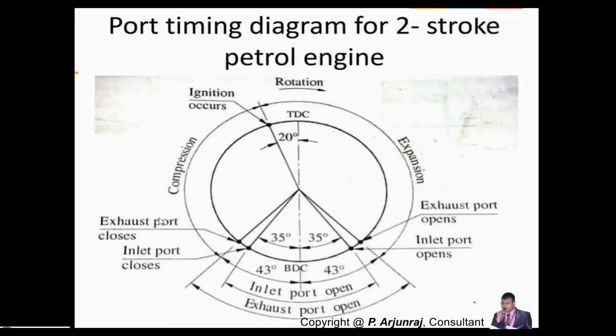The transfer port is the one which will transfer the air and fuel mixture to the combustion chamber above the piston in the case of a gasoline engine, whereas in the case of a diesel engine, it will transfer the air to the combustion chamber above the piston, and then the air will mix with the injected fuel in the case of diesel. And the exhaust port will expel the exhaust gas. So the inlet valve is similar to the inlet port, and the exhaust valve is similar to the exhaust port. But you also have the transfer port.